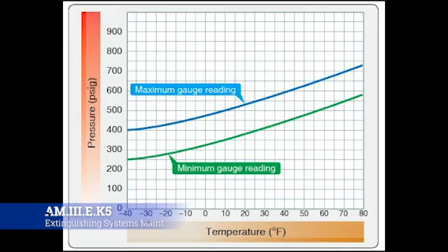The main thing is don't accidentally blow a fire bottle. That's the main maintenance task. Looking at the gauge and all the other stuff is easy. The main thing is respect those fire bottles whenever they're on board that airplane, and don't accidentally pull a fire handle or do anything, especially if you're doing some sort of troubleshooting that requires you to mess around with the fire system. Once that bottle goes, there is a sea of work and money that comes behind it. So you want to be very, very careful with playing around with them.